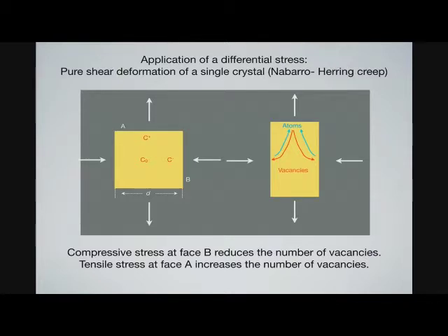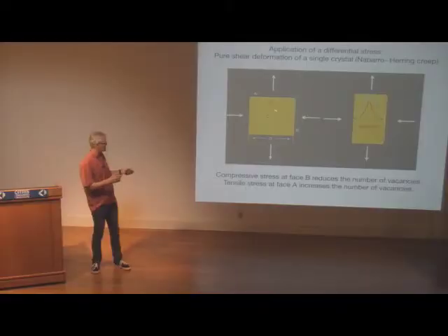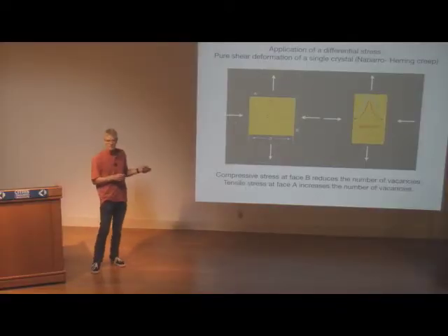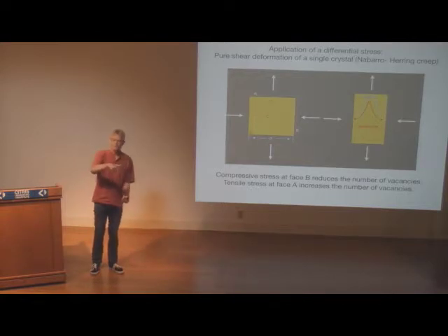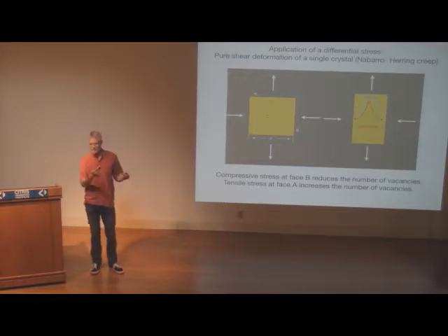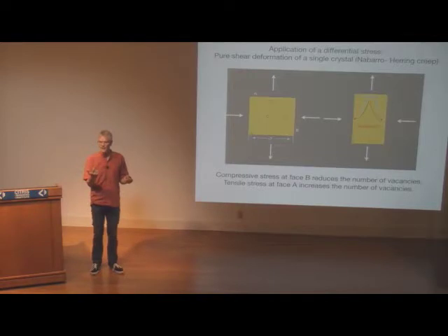You can sort of imagine that if you have a higher stress in the horizontal direction in comparison to the vertical direction, and all stresses in the Earth are always compressive. Here it's drawn as a tension, but it works with different compressive stresses. So you have your sigma 1 and your sigma 3. Sigma 1 would be the dead weight. Sigma 3 would be the confining pressure of the surrounding air in your dead weight experiment.